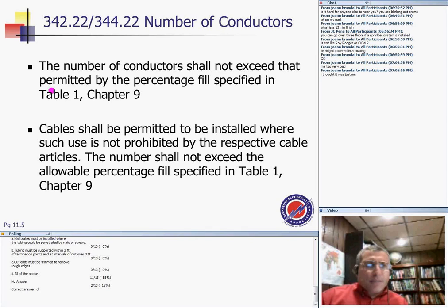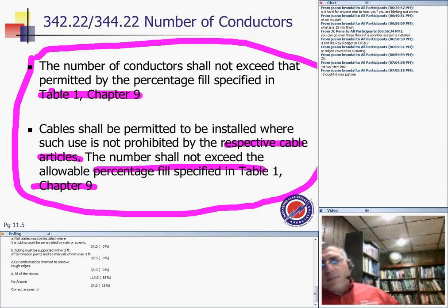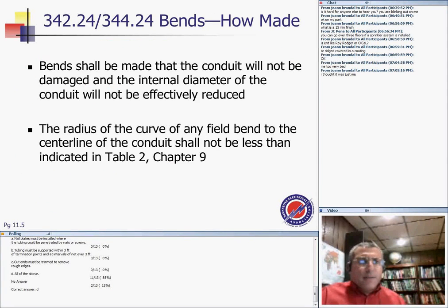Structures, exactly the same location, guys. If you go to Table 9, Chapter 9, and see, if all the conductors are the same size, the NEC tells you how many conductors you can fit in a 3/4-inch rigid. The same if the cable is allowed to be installed in conduit, you can find how many cables you can install. You treat the cable as one conductor, as a matter of fact. Any questions? By the way, this will repeat itself for all the conduits I'm going to discuss tonight. Go to Chapter 9 to find how many conductors you can install, and I can go there with you.